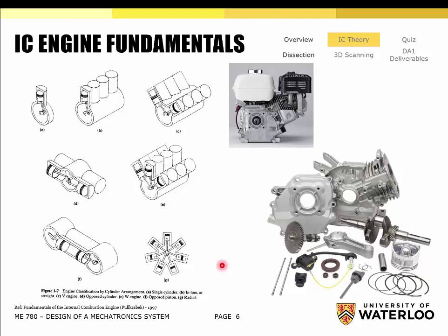Finally, this is quite common in airplanes, and I'll ask the class why they might think that's the case. This is the radial type engine. So that uses one crankshaft, but instead of having a V of multiple cylinders, it just copies that V multiple times around the circumference of a circle, okay? So why might you think that would be useful on an aircraft? Yes? Propellers. Propellers, okay, what about the propeller makes it useful? It allows the propellers to rotate properly. Okay, so generally in an aircraft, the propeller is mounted to the front of the engine, so he's saying that it allows the propellers to rotate properly. We'll talk about that a little bit. Anyone else? Yep.